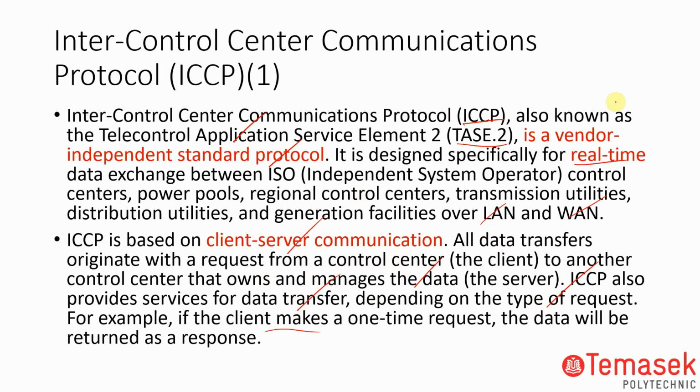The key portion over here is real-time. How real-time is it? When you go over the WAN, you're subjected to network time protocol. On your LAN, as I mentioned just now, if you manage to put your network as a TSN network, time sensitive network, which is using IEEE 1588, then you are running on PTP, precision time protocol.